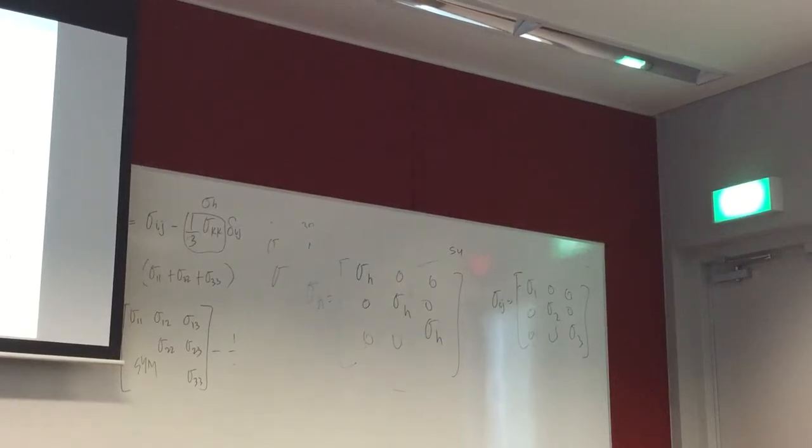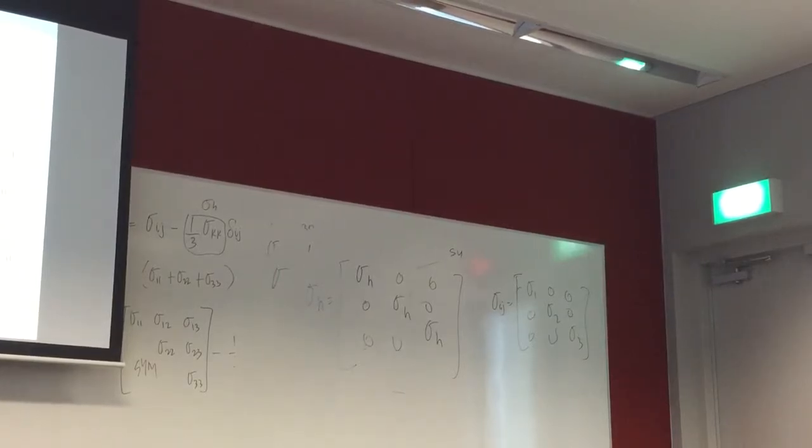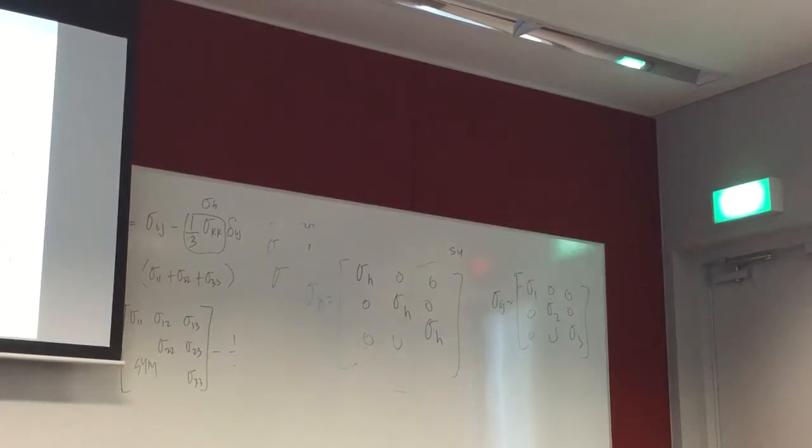What does this one say? Now that we have proven that a hydrostatic stress state won't yield, what does this mean? If you just have a uniaxial loading, then your material will yield once your applied stress is equal to the yield strength of your material.